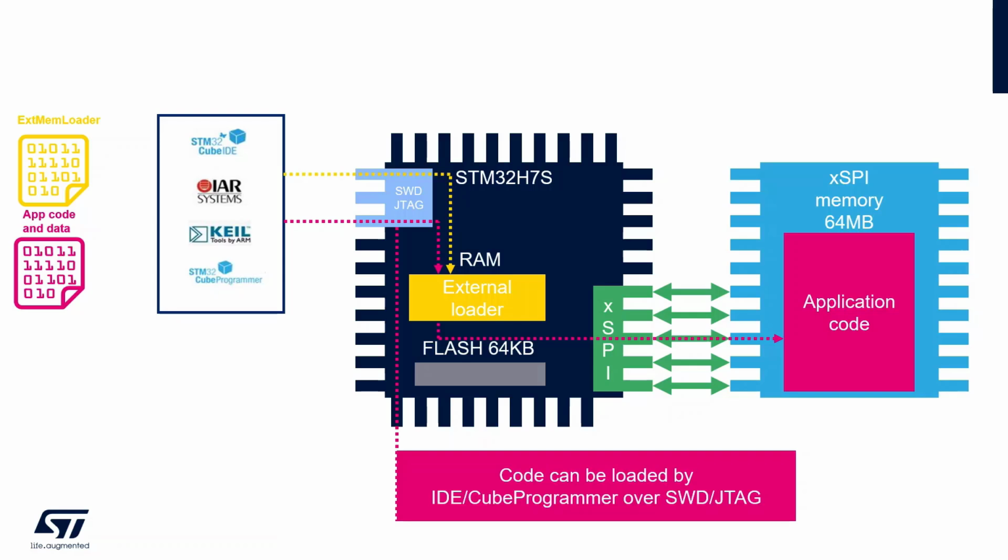And it will take this project, this external memory loader, put it into RAM and use the functions from this project. So it's not a normal application, it doesn't have a main. It mainly has the functions which were defined by the Cube, by the programs which will be using this loader, which need to be there, and they will call them specifically during the programming.